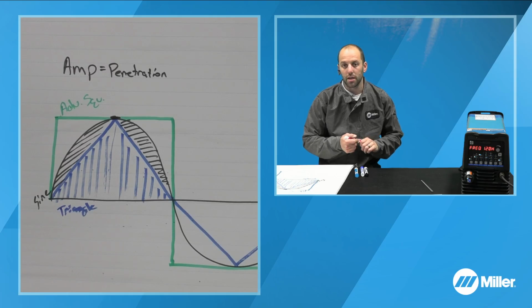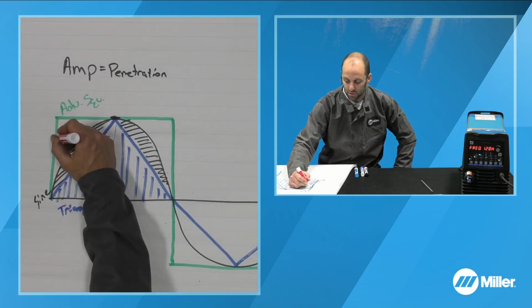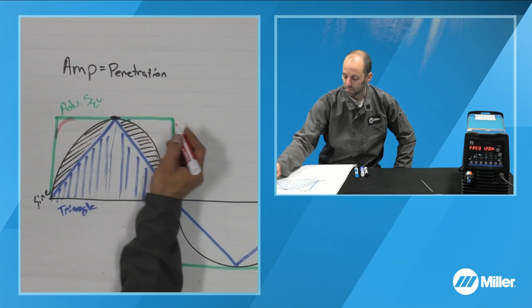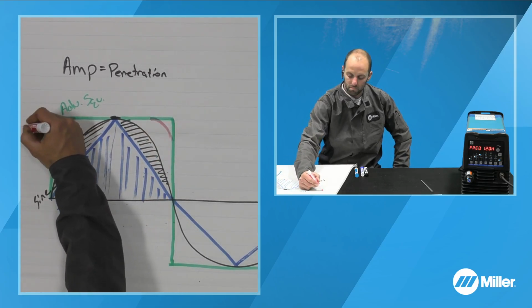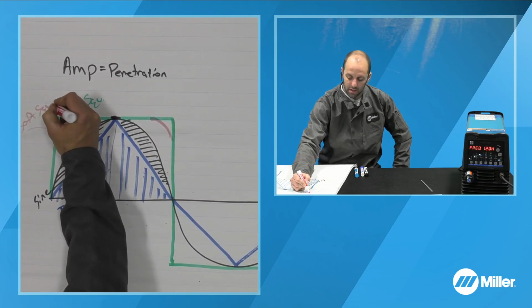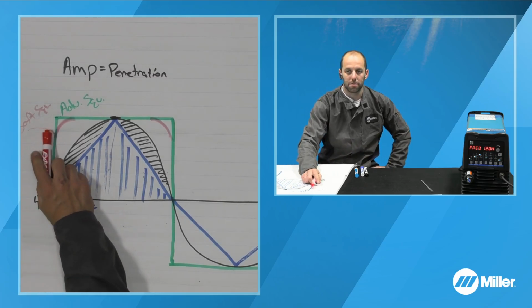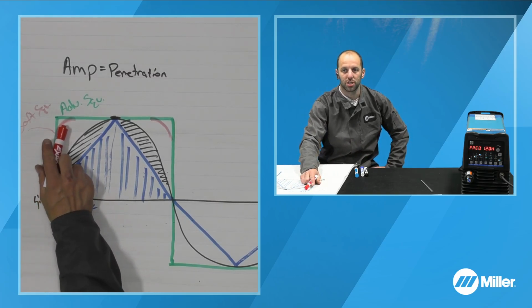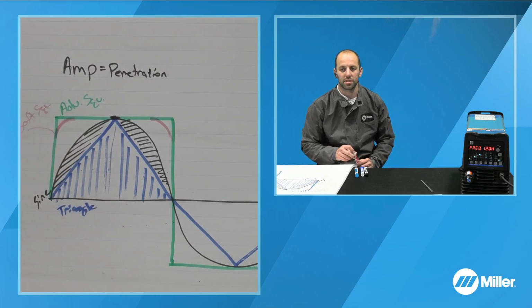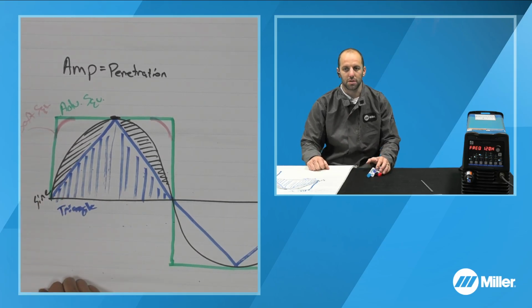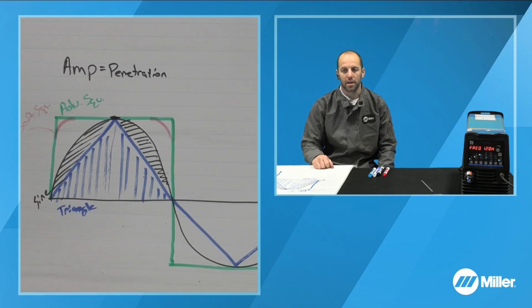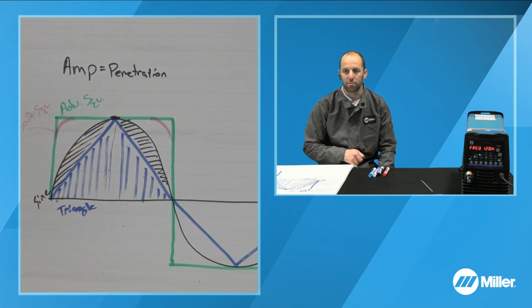So what we've done is we've also brought in the soft square waveform. So we round these corners off slightly, not drastically changing the amount of heat input, but it does have a pretty significant difference on the noise level, because we're transitioning more smoothly as we get up to our high welding current or high welding amperage. And so from a welding perspective, that's where I prefer to be. That's where the factory defaults on, for example, the Dynasty product are, and it has a much more appealing noise level as compared to maybe an advanced square waveform.